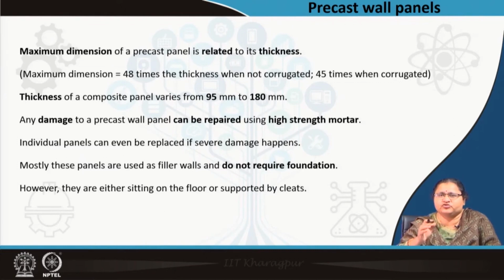These walls are usually used as filler walls within a structural system. So you may have a beam column system where these walls will go and just rest. It is completely dry, unlike the CMU blocks or the AAC blocks which we had already covered. So they may start or initiate from sitting on the floor beam or special members called cleats.